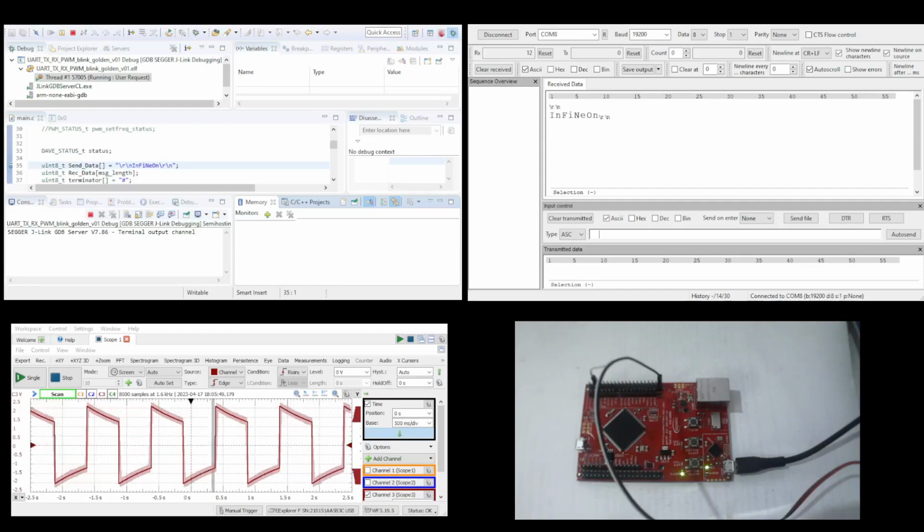In this sample code, the receive word length is 2 bytes. The data received from the UART is used to modify the duty cycle of the PWM signal. With every data being sent from the UART port, the duty cycle of the signal being generated changes, and it can be observed on the oscilloscope.